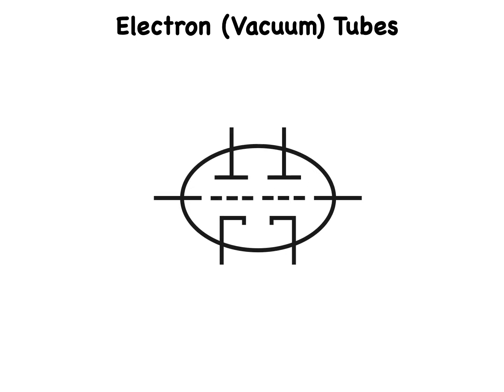Some vacuum tubes consist of 2 separate, independent sets of electrodes housed in a single envelope. These components are called dual tubes. If the 2 sets of electrodes are identical, the entire component is called a dual diode, dual triode, dual tetrode, or dual pentode. This shows the schematic symbol for a dual triode vacuum tube with indirectly heated cathodes.